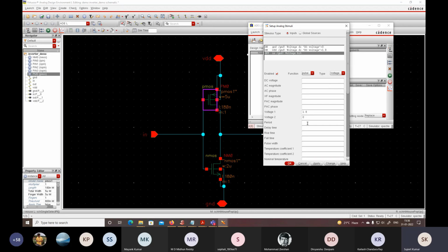Let's say we give a period of 50 nanosecond, so the pulse width is half of this, 25 nanosecond. You can choose the rise time and fall time, but it is not necessary. You have to play with different rise times and fall times, and you can check your characteristics.